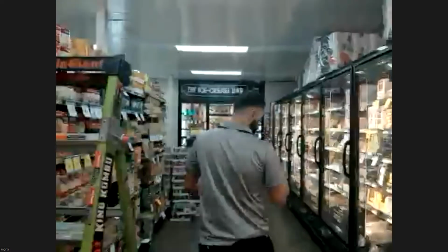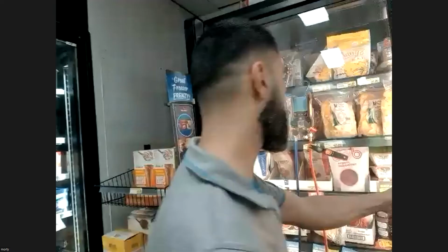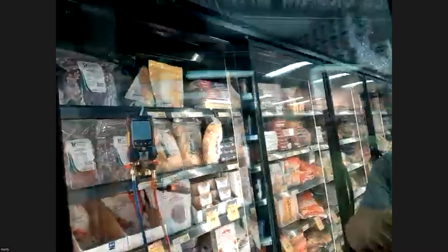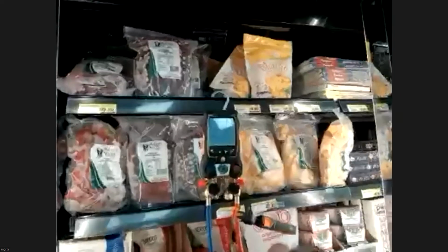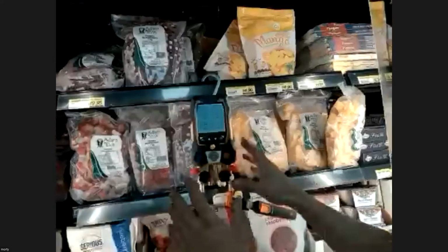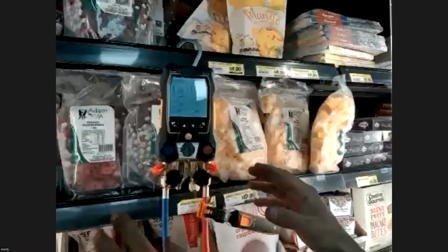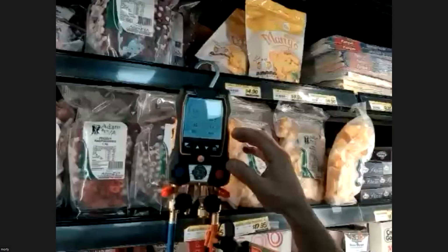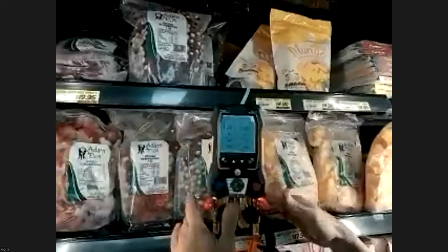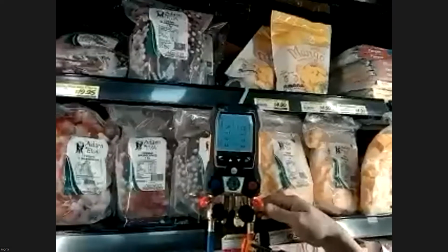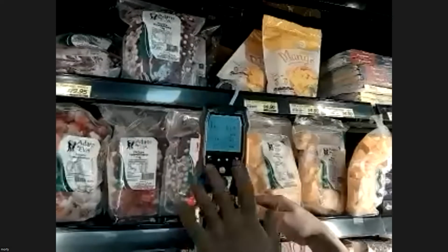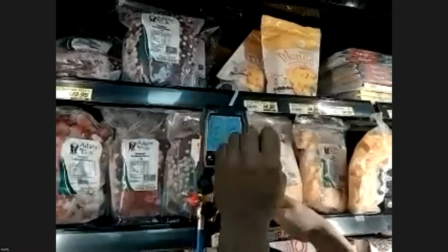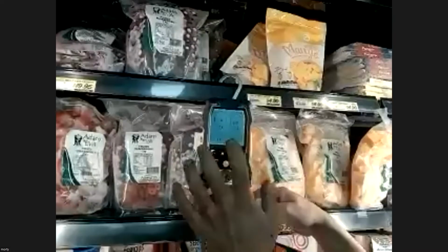So I'm going to take you through the system now, and we'll talk through it. We can show you the screen on this one here. So come around. The system is on, so we'll try not to keep the door open for too long. When you connect the gauges, especially electronically, you want to get the system inside the freezer. Give it about 5 minutes before you start taking measurements, whether it's mechanical or electronic. We have already done that, so we don't have to wait around too much.